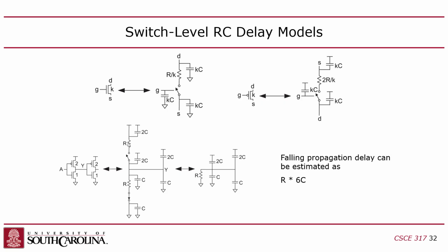Then on the input inverter, now I got gate capacitors on that guy. So this is the input capacitance of the downstream inverter, the gate I'm driving, the gate I'm sending my output to. This is C and 2C. Why C and 2C? Because remember, I'm driving an inverter. An inverter has 2 transistors, a P and an N. I got to drive both their gates. Both their gates are capacitors, right?